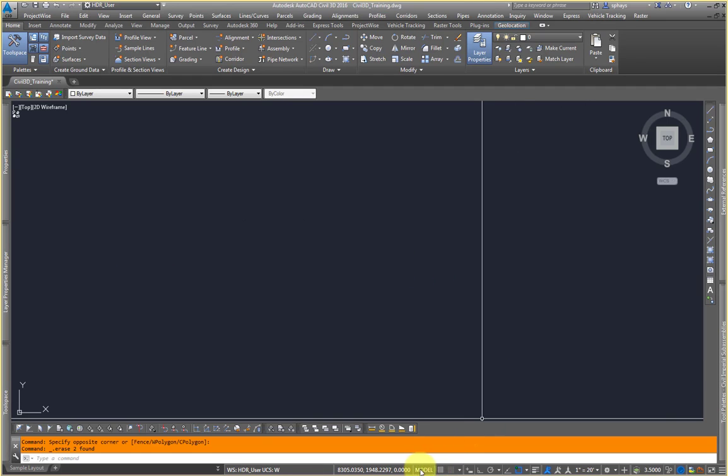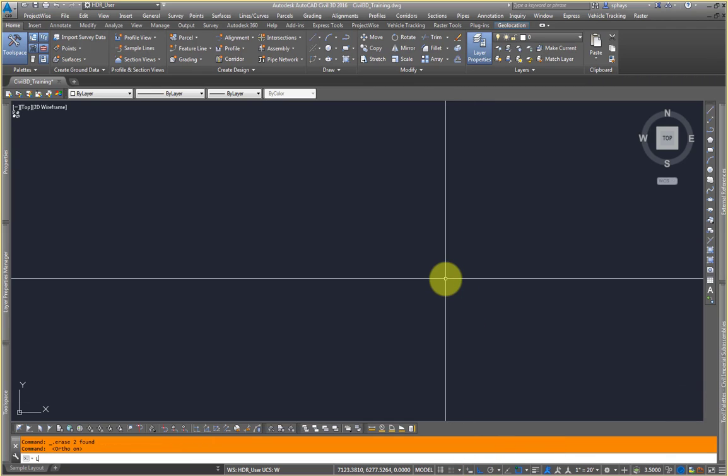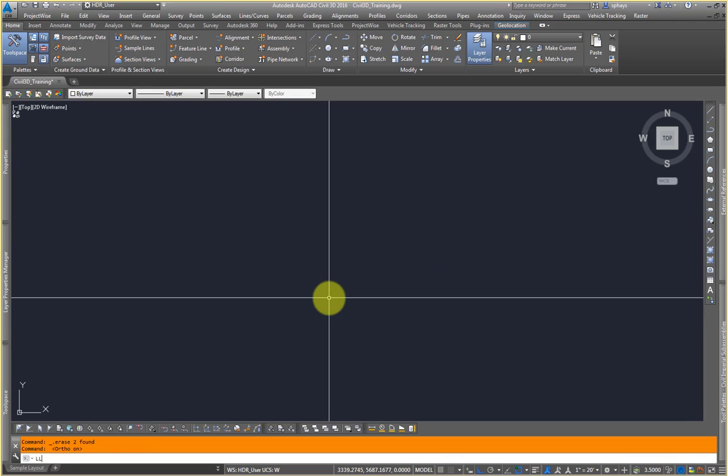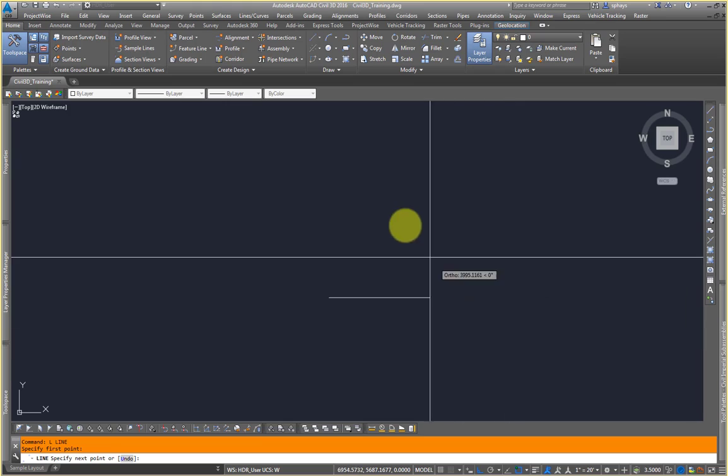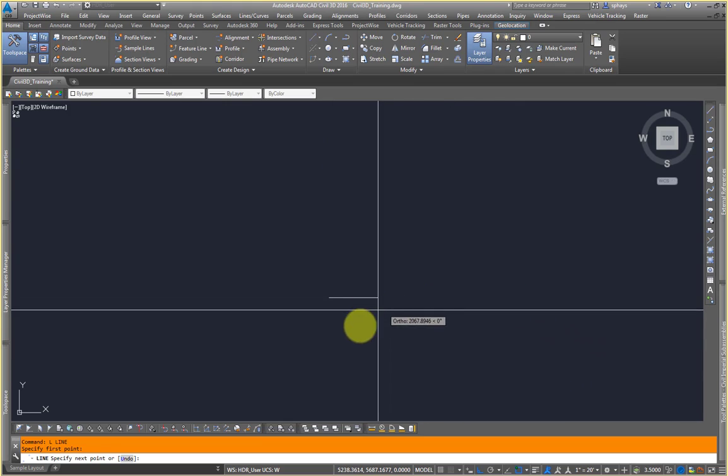Okay, so let's talk quickly about our tray down here. Our tray has a variety of different uses. Like I said, we have our object snap. We also have ortho. If you want to turn your ortho on, whenever you draw a line, it'll automatically be drawn orthographically.